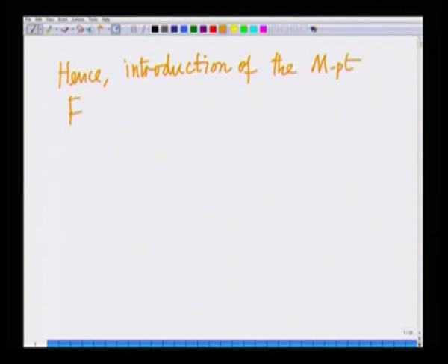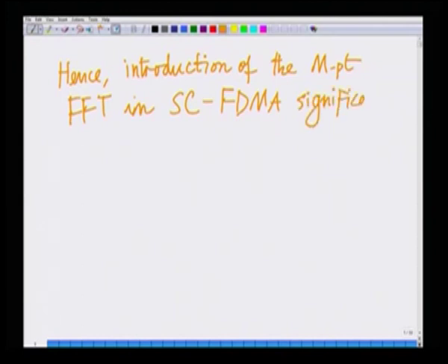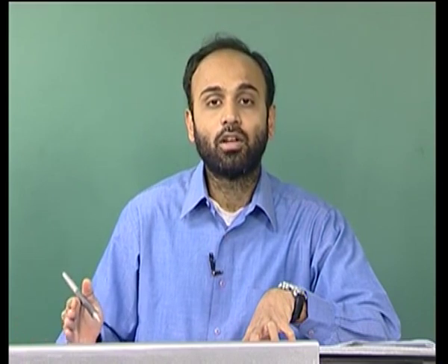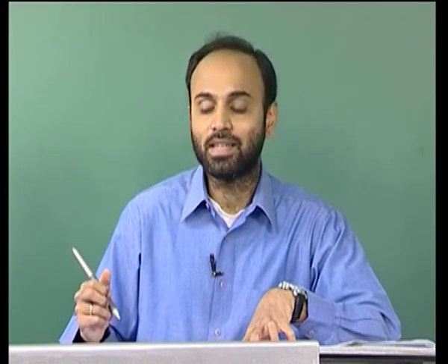of the M point FFT in SC-FDMA significantly reduces the PAPR of the system, and this is essentially the SC-FDMA scheme, which is single carrier FDMA.